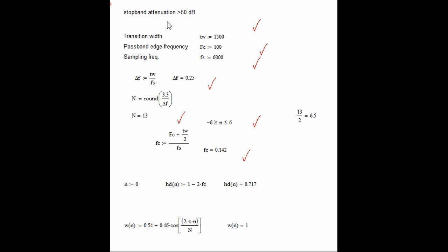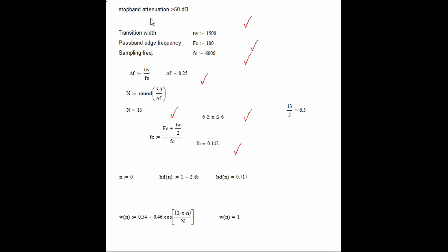The next thing, I want a low pass filter or high pass filter or band pass filter. In my case, a high pass filter. Of which ranges, because you have to decide where your filter must be. So your cutoff is going to be important, your transition width is going to be important. Sample rate, the speed of your processor. So these will be given.